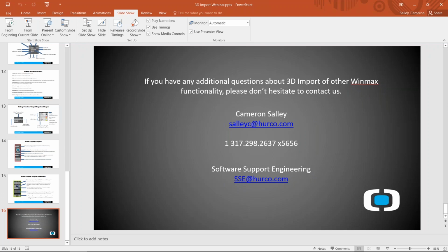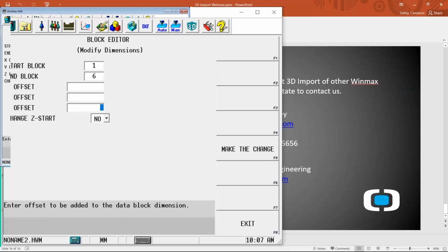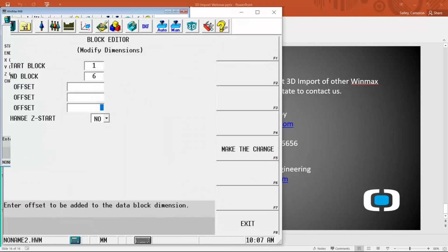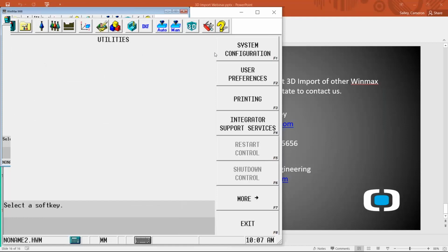We got one more question. Any chance that the 3D solid model will run in another type of program besides universal type? No, is the answer to that. With universal program types, you're going to be locked in. So you can't use rotary A or tilt A, rotary C. You are going to be locked in at the universal program types.